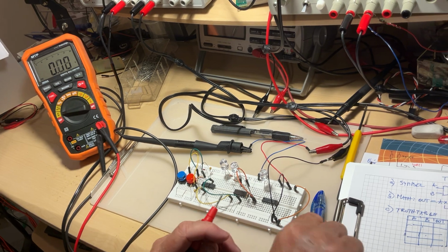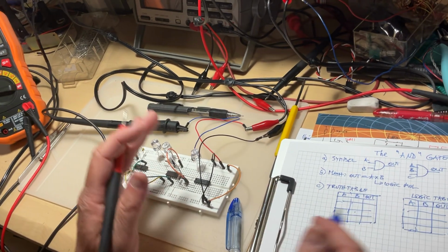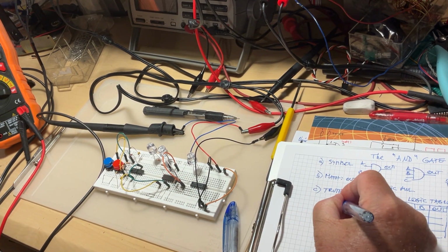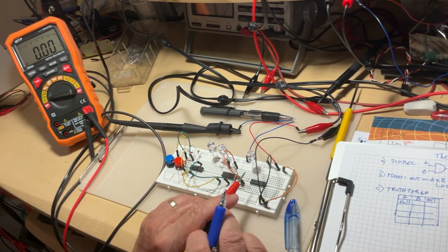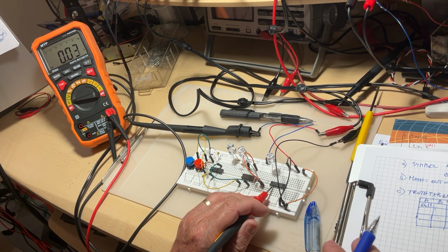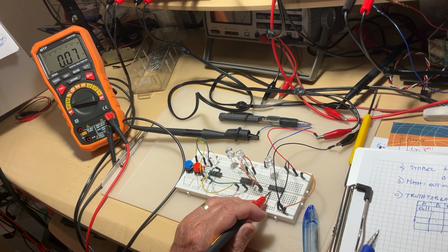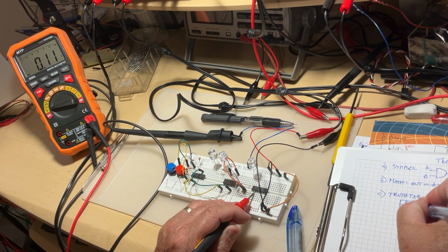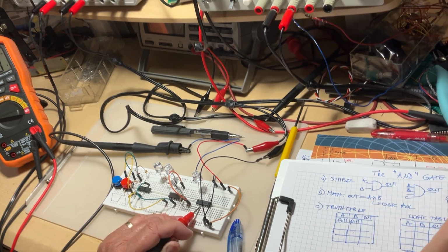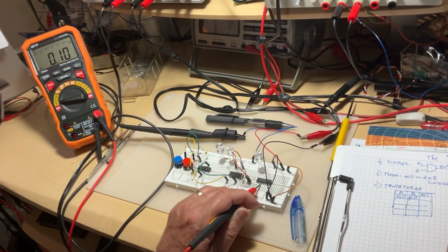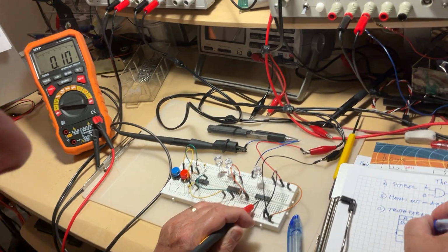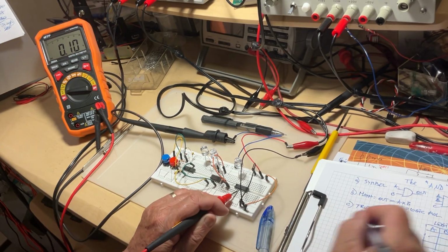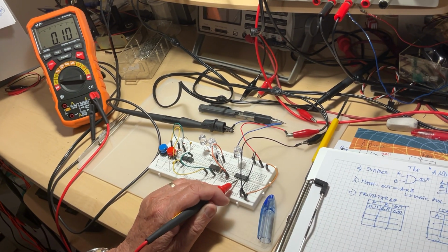So here, initially, when both inputs are off, we measure here what I can see. 0.11 volts. I write it down. I don't judge, I'm just writing the voltages. 0.11. B is right here. So what do I read? Similar voltage, 0.11. What is the output? 0.10. All the measurements are in volts, okay?